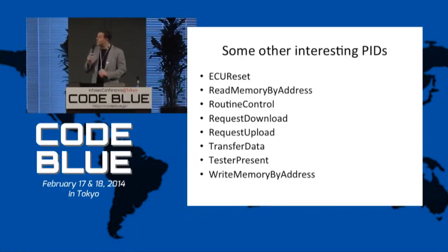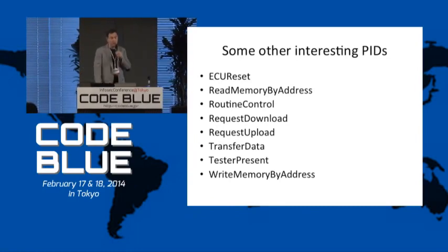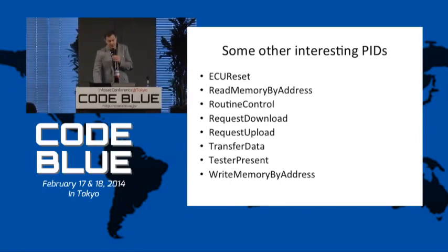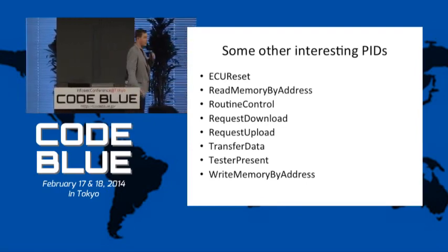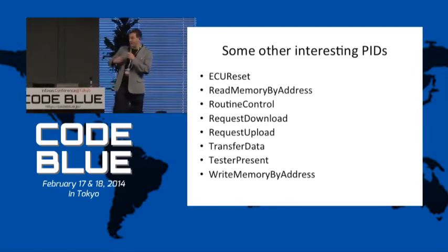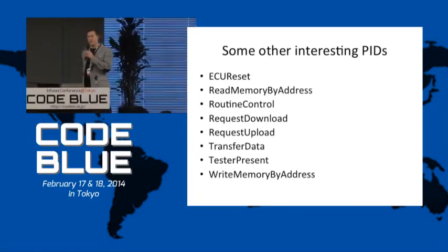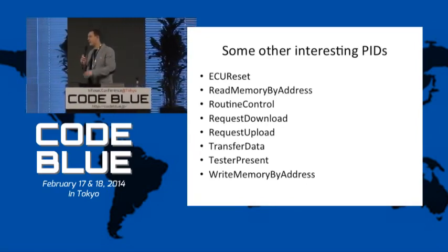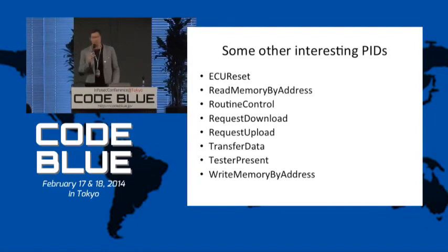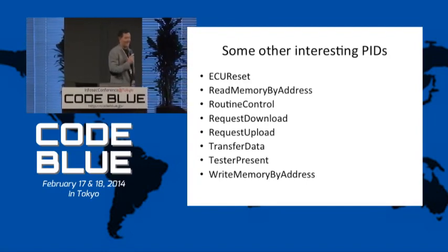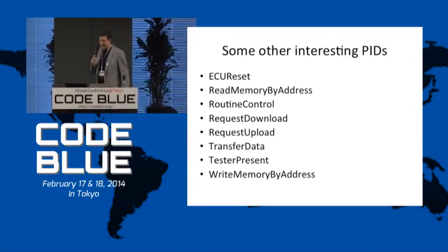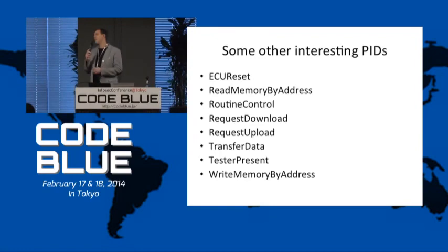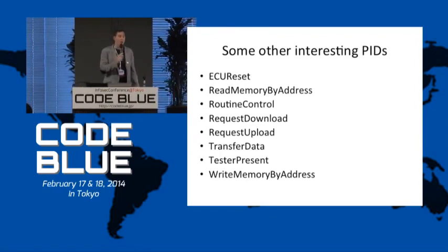Originally, when we started doing this research, we got super excited because we saw services that were defined as request download and request upload, right? That's give me your code off the ECU, here's code to put on the ECU. We figured car hacking would take us all of 3 weeks, we'd be done, and we'd be internet famous. Needless to say, while we did gain a bit of internet infamy, these services aren't always included and almost never are included.